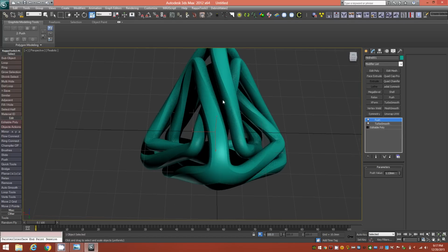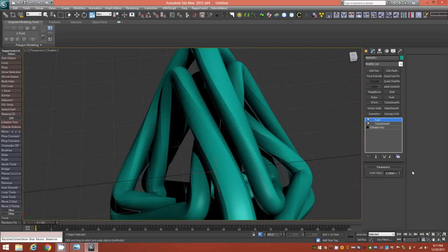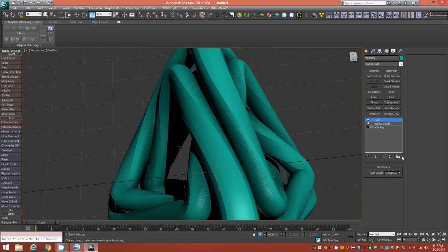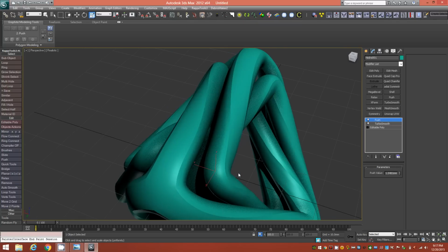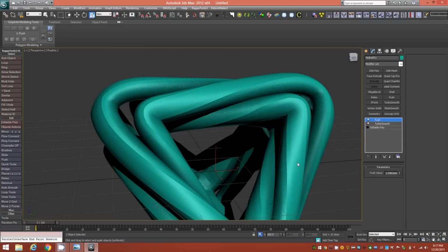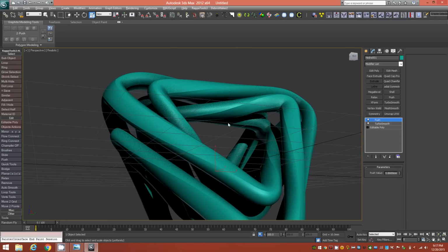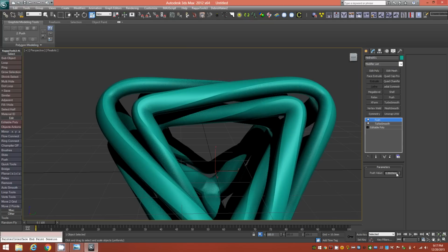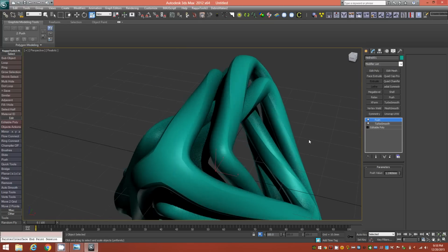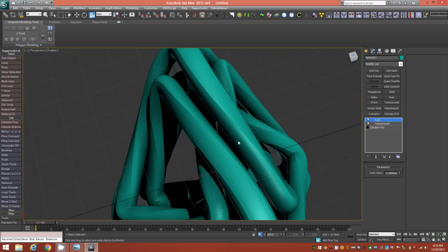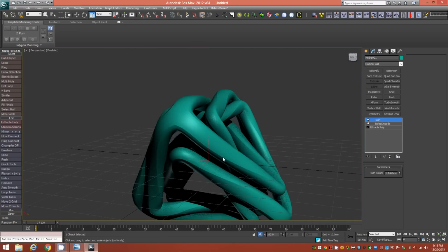And also, if you're going to 3D print, be careful of the distance between your joints here, or your struts, not to come so close as to cause it to have trouble printing. So just be mindful of the tolerance space that your 3D printer will have. In the case of Shapeways, you can go pretty thick and come pretty close.